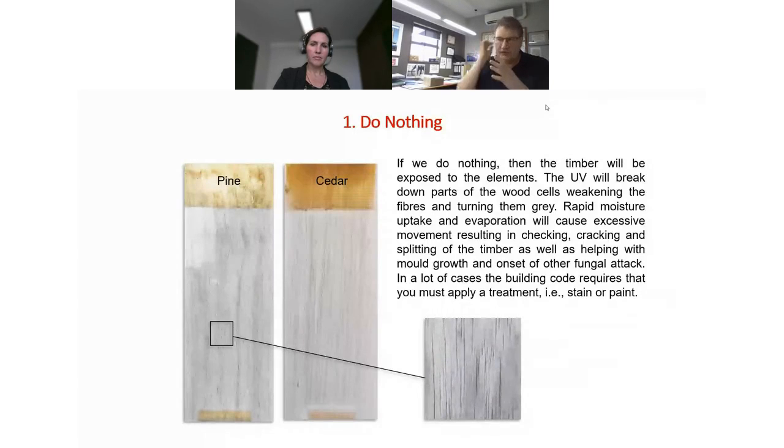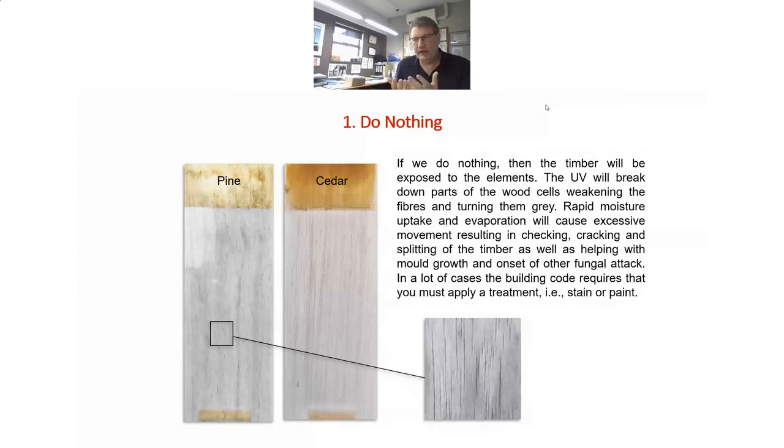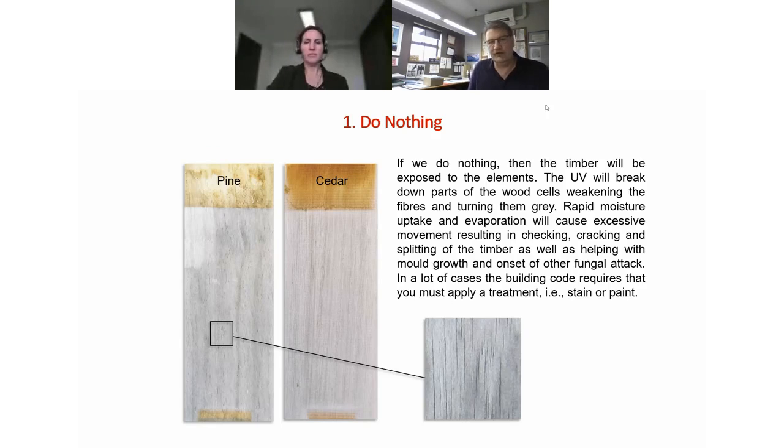And you'll see the grey, and it's important to understand this too. All the things that are inside, there's these little pigment parts of timber which make up the colour. They're water soluble. So they get washed out by the weather. So that's why your timber goes grey. And you can see those little darker black stains starting to show up in there. Well, that's your mold. And mold eats the carbohydrate sugars that are brought to the surface by the water. And it's just nature. Mold is natural. So if we do nothing, that's what you could expect.